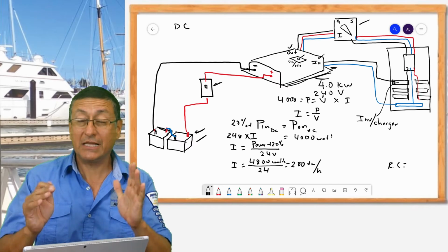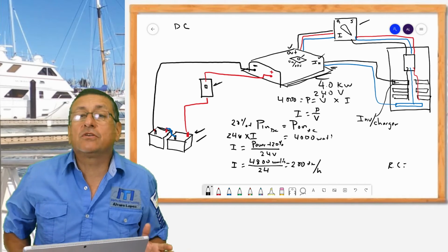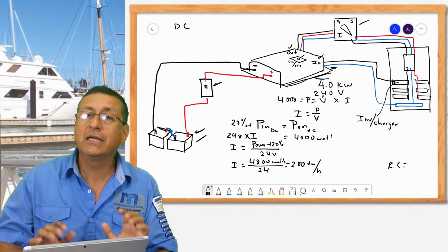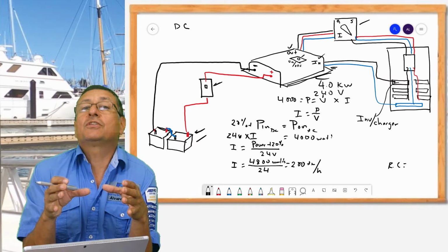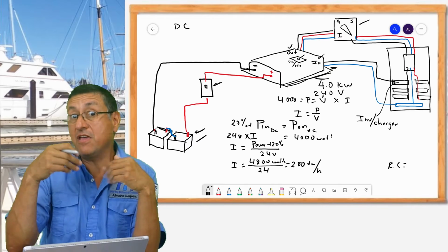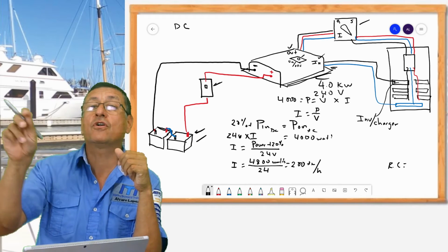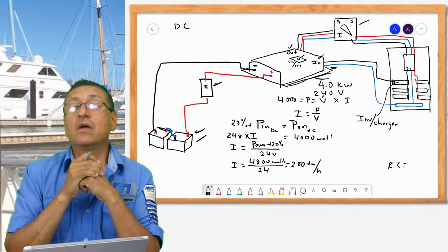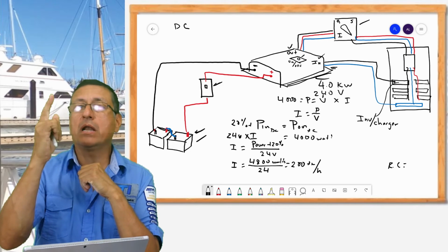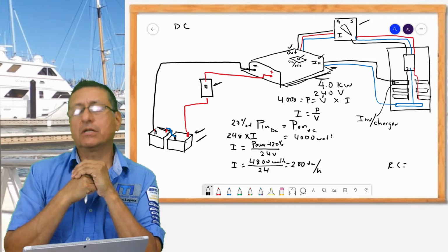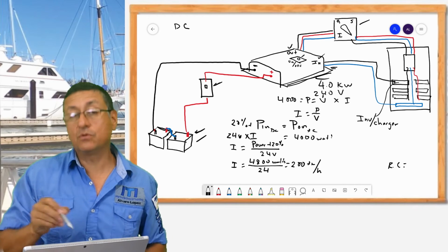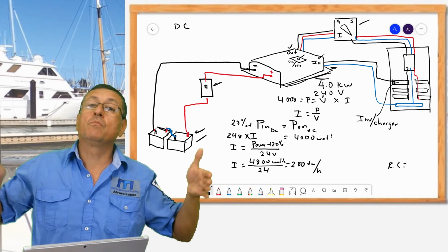Okay? That's good? Okay, this is the situation. I need 200 amp-hours in the configuration of my battery bank in order to keep my inverter running, producing 4,000 watts in 1 hour. If I need 3 hours, you multiply 200 times 3 and you need to put more batteries.